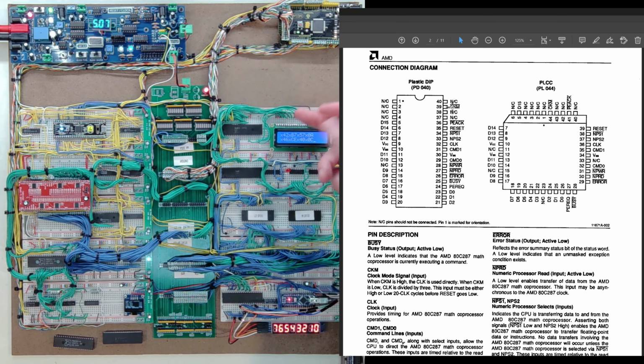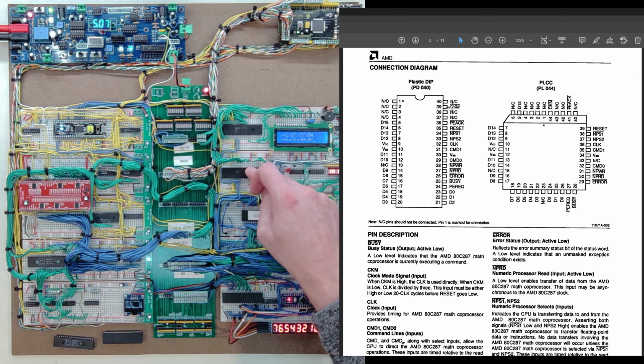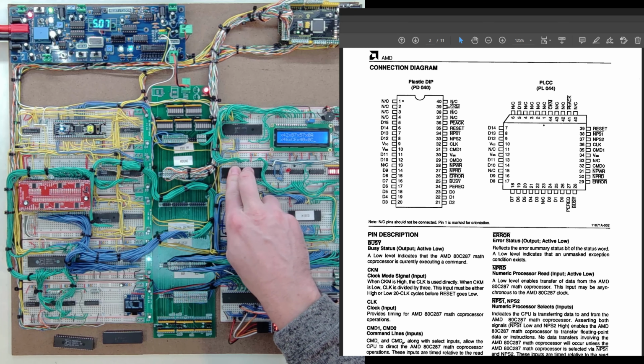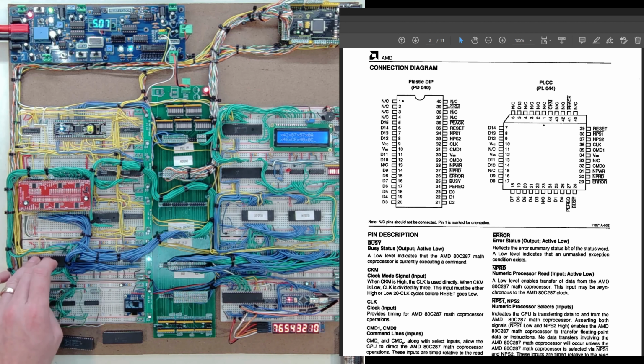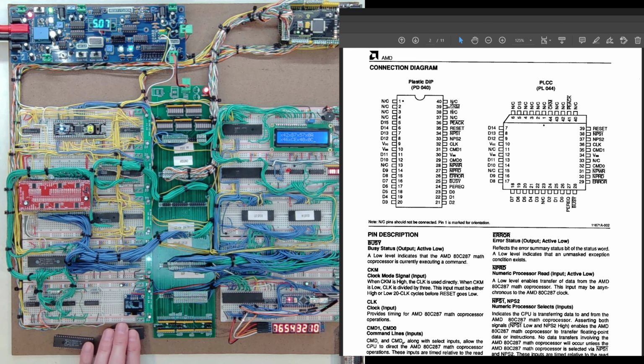My expectation, I guess, is as I swap out these next two PPIs, that will also come down. And I do also notice that these CMOS versions are perfectly cool, whereas the older TTL version got quite warm. So that is also nice to see. If you have any feedback on that, let me know. But I think ultimately the solution was a different inline resistor on my clock.